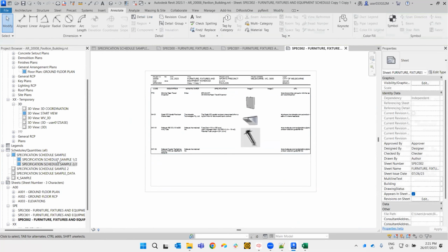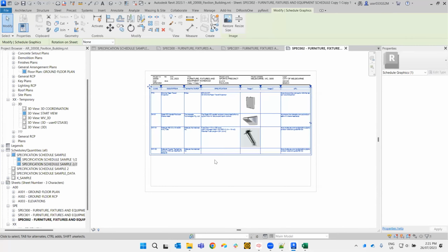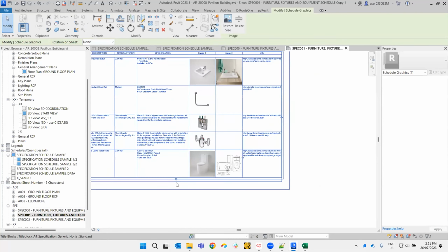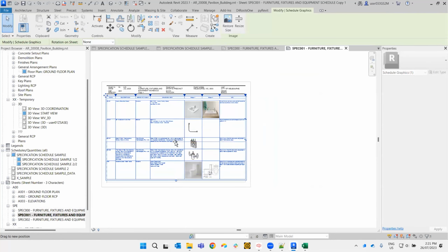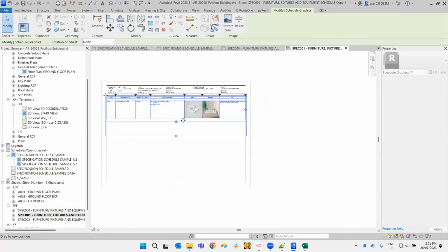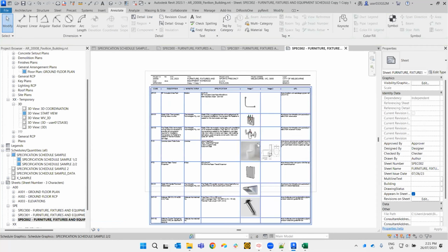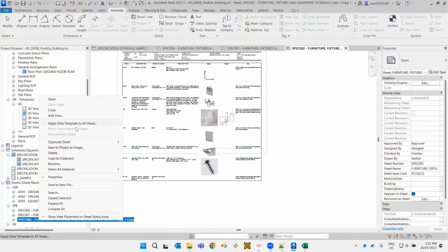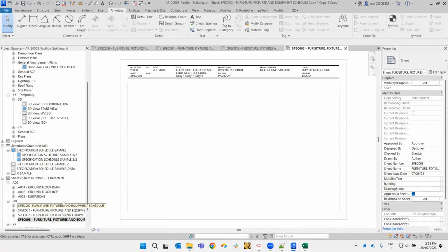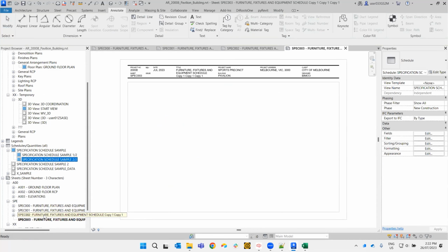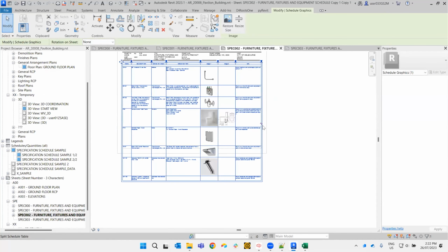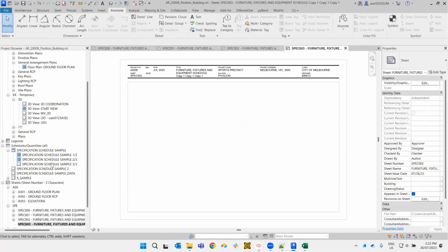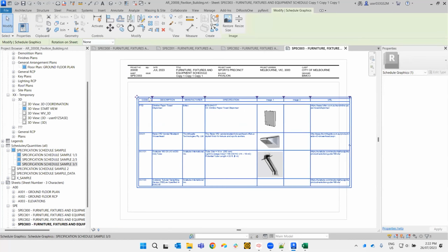Now the nice thing about that is as items are added, it will actually be defined by the height of the schedule. So if I go into this one here, we've actually got a grip here. If I drag that up just to 1 or 2 items, I go to my next sheet, you can see that it's pushed it out, and then we could just rinse and repeat, duplicate this sheet. Okay, we want to split out our schedule again. So click this guy, split it again. You can delete this bit, go to our next page, drag on our part 3, like so.